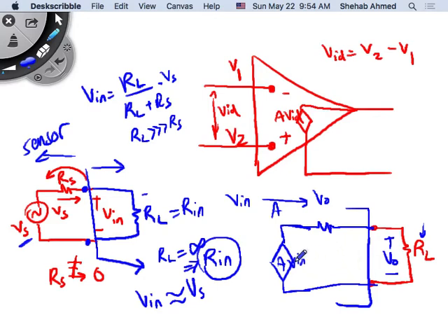Still a terminal equivalent. It's an equivalent circuit. Any physical phenomenon, any voltage source can be modeled as an affine dependent or independent source with a series impedance. So it's still terminal. Yeah, any physical phenomenon. Okay? Even power system generators. A power system generator is modeled as a voltage source in series with an impedance.